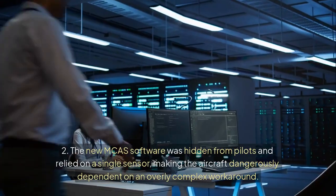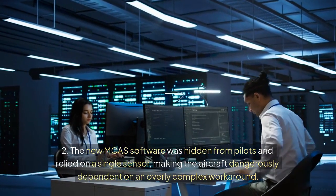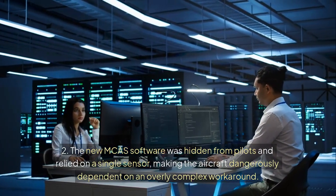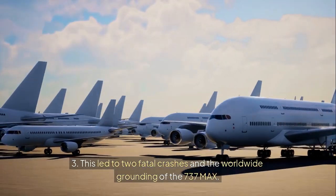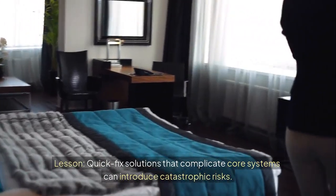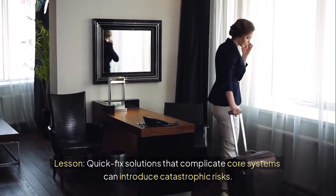2. The new MCAS software was hidden from pilots and relied on a single sensor, making the aircraft dangerously dependent on an overly complex workaround. 3. This led to 2 fatal crashes and the worldwide grounding of the 737 MAX. Lesson: quick-fix solutions that complicate core systems can introduce catastrophic risks.